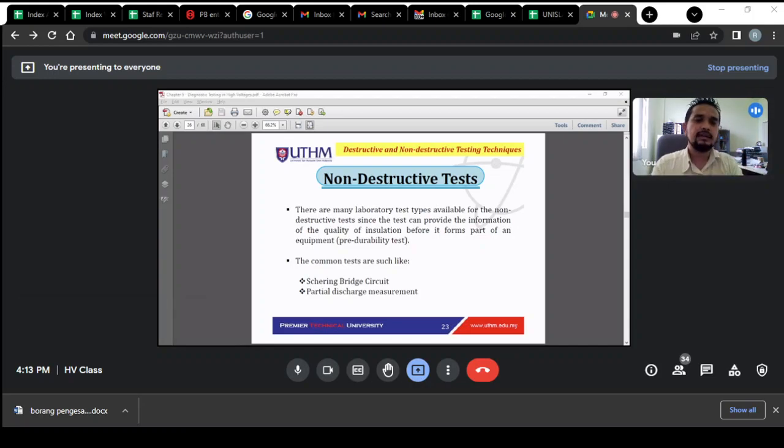And then we should be able to capture the voltage rating, and we can observe at what point the insulator will fail to operate, meaning at what voltage level it will trigger the flashover. It is not necessarily in the cross arm arrangement. Cross arm is one of the examples. You can test a sample of the insulator as small as two finger size. It depends on the application. Don't get it wrong, it's just an example.